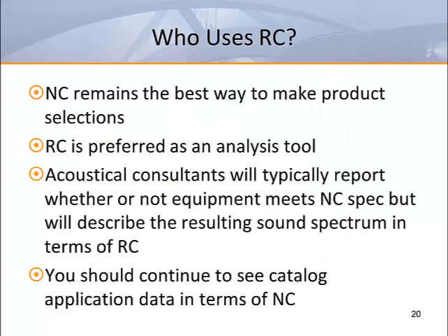It's rare to see any manufacturer's catalogs referencing RC, so exactly who's using it? Acousticians like to use RC to explain why a sound environment that meets a specified NC level may be objectionable to an occupant. After the NC has been verified, it's common to see an RC analysis used to explain the nature of the problem along with suggested solutions. Don't expect to see NC levels disappearing from manufacturers' catalogs. NC remains the preferred method of equipment selection.